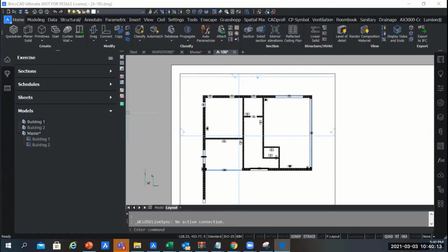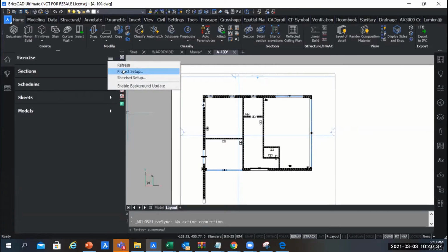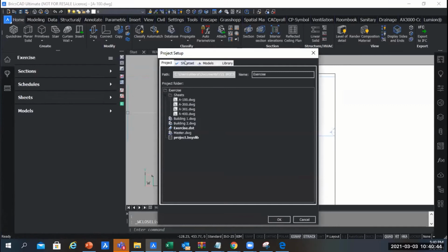I think what we can now do is, we are on page 48, right? We're done with 45, 46, 47. We can quickly do edit the project. To edit the project after creation, you can go to the hamburger menu in the top over here. And then you can click on project setup. Then we get the same dialog as upon creation. And then you can start editing this.